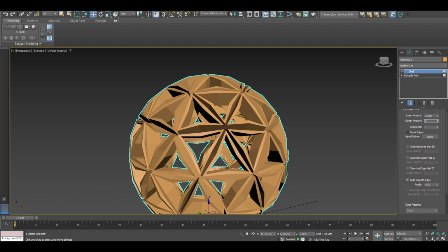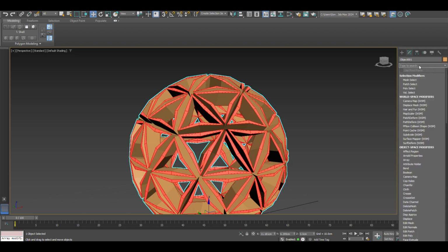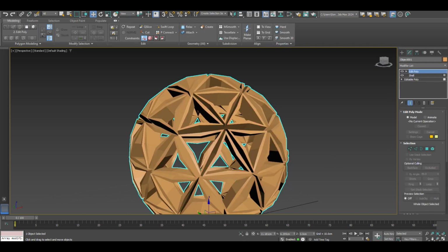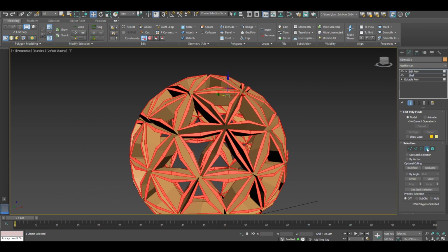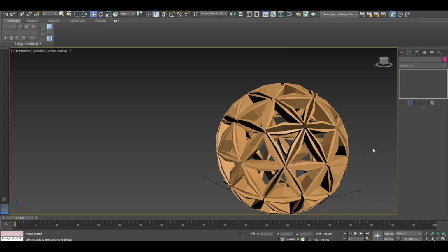Change the outer amount to 1.3 in the shell parameters. Again, apply entity and point to the object, and select the surface. Do we need to apply any other option? I think so. I think we are good.